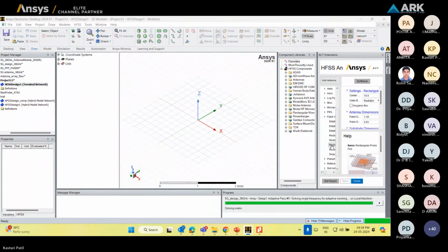Rectangle, a coaxial rectangle probe coaxial tube. So here it is operating at 28, but I'm changing its dimensions also. It's not exactly what I get after calculation and synthesizing here; I'm not using the same, I'm going to change those things. It is operating at 28 gigahertz. I'm using the substrate as Duroid.